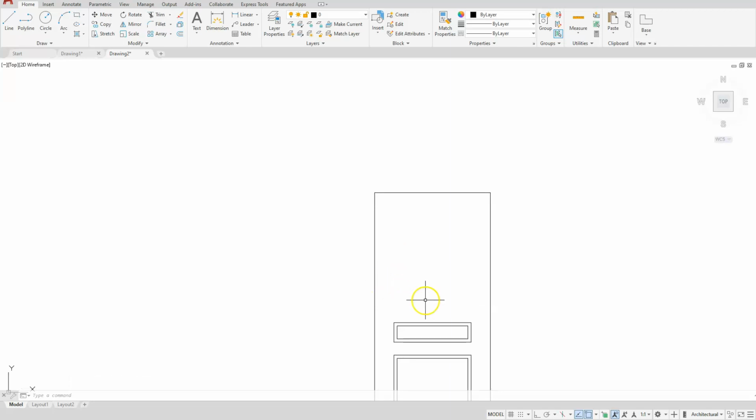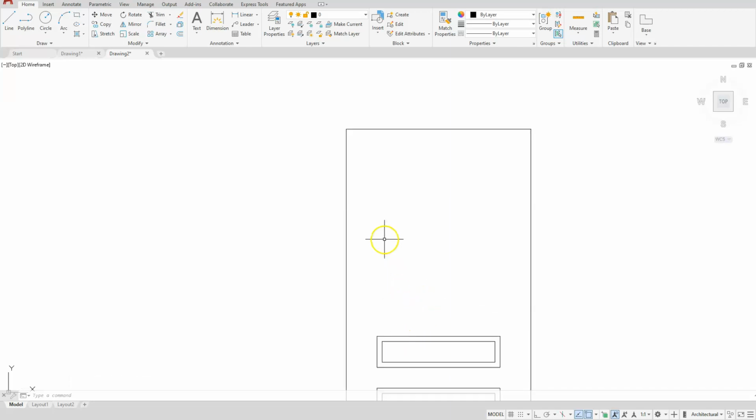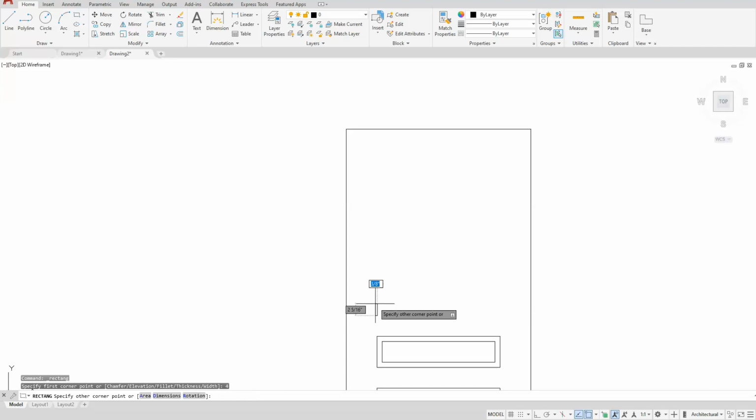Okay, so the next thing I need to do is create the shape that's located here. The width of it is 10, and the height of it is 2'6", and it's another 4 inches away from that line created. So let's go to the rectangle command. Touch the endpoint, track away from it, type in 4, enter, and then I need to give it the dimensions. The X dimension in this case is 10, comma, the height is 2'6", enter.